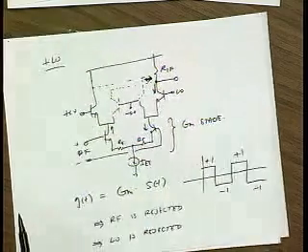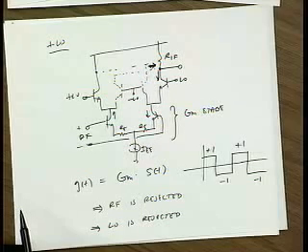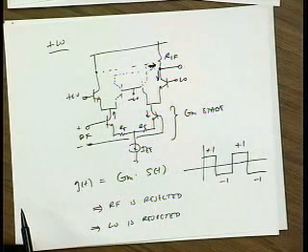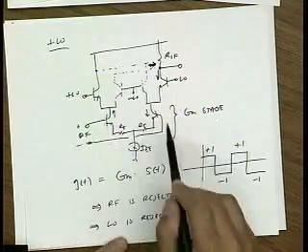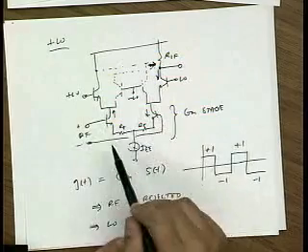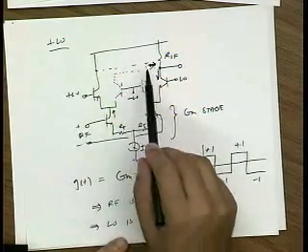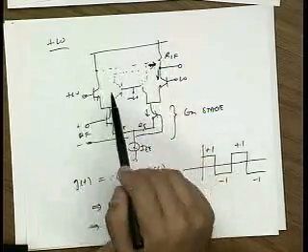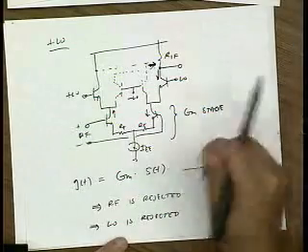Yes, Debo. So in single balanced mixer, we saw that when we took the output differentially, the gain was doubled because of the square wave. Here again, if we now take differentially, will it again be doubled? Yeah. So it will be plus 2 minus 2? Yeah, definitely. Well, it's not doubled, it's not plus 2 minus 2, because then the input is degenerated. It's a differential pair. So we get half the gain down here, right? And then to recover the gain, we could take it differentially output. So for comparing apples to apples, the gains are the same.